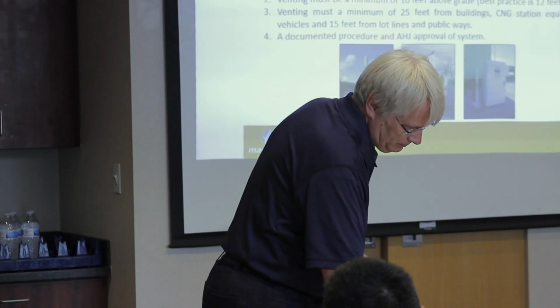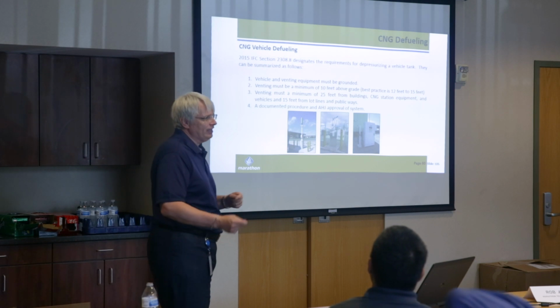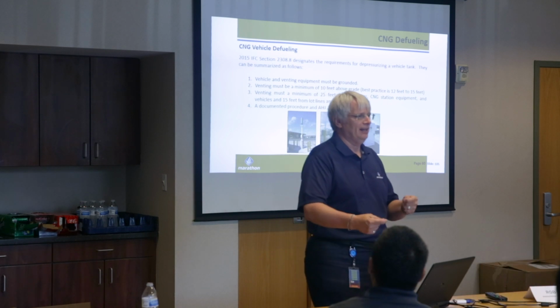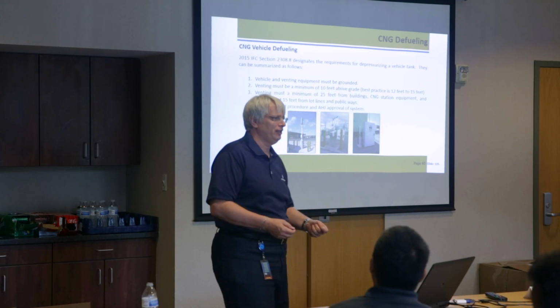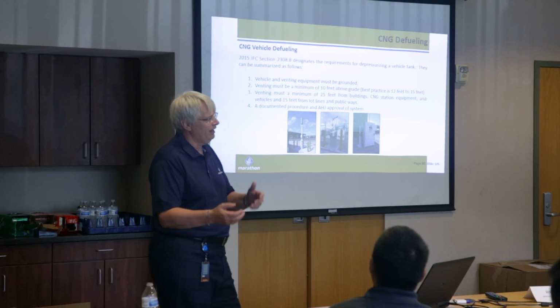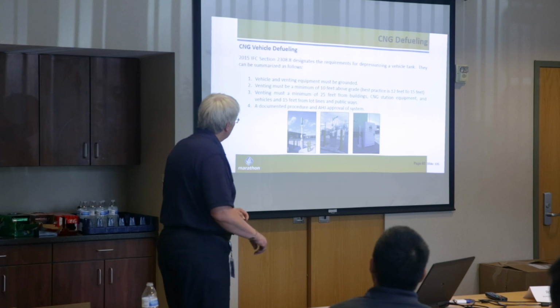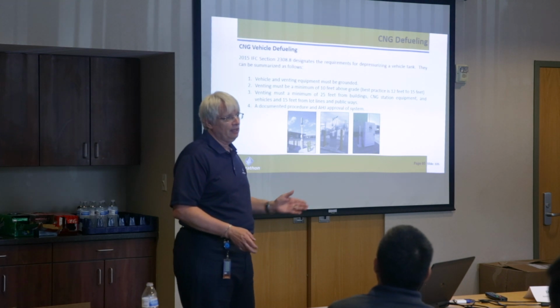Okay, so we talked about defueling. I don't want you to think I'm anti-defueling. I'm just anti-defueling unless you have to. And in most cases, you don't have to. There will be a way of isolating the fuel on the vehicle and making whatever repair is required without defueling. That being said, there is a requirement for defueling.